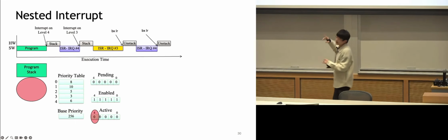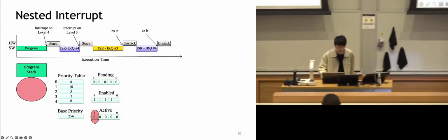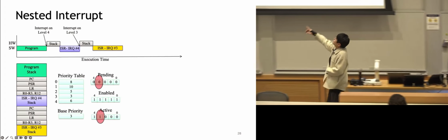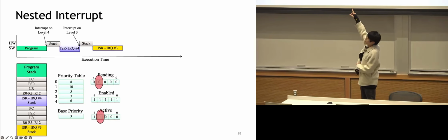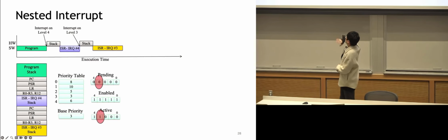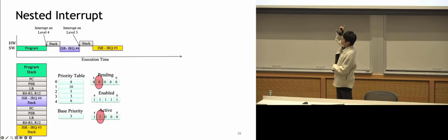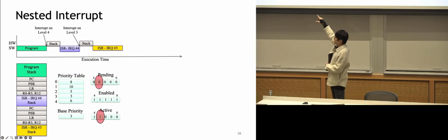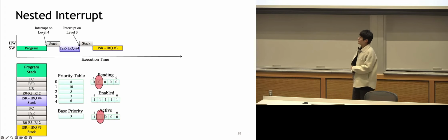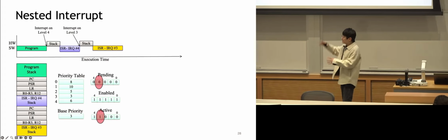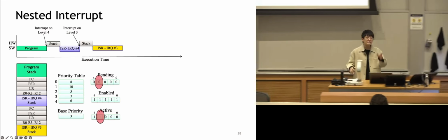Imagine here, this interrupt index 3 is periodic, and it just happens to be 1 at this stage. On the peripheral side, it determined to do another read or another interrupt from the peripheral. So the peripheral sends another interrupt request to the NVIC. On the NVIC, it will put that pending bit up, although that interrupt is currently being executed. Yes, but if there's only 1 request, usually they will not be on at the same time. If you have multiple on the way for the same interrupts, yeah.